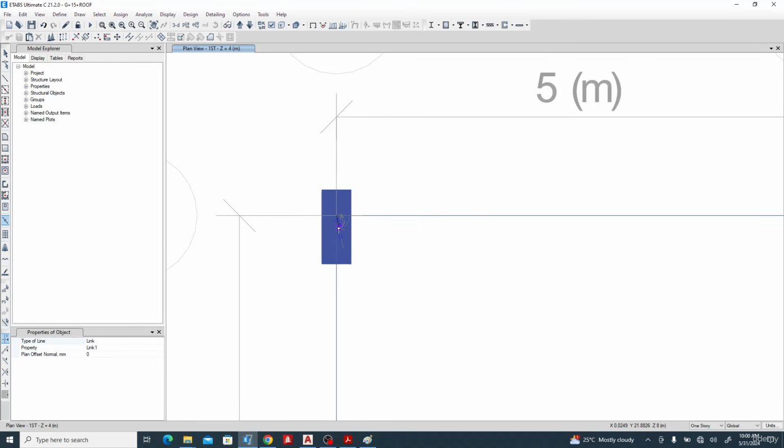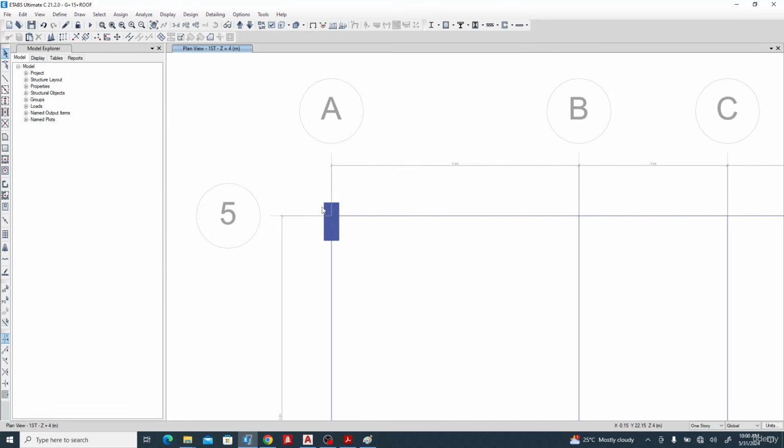Okay, now maybe the next office is okay. So you can draw these links. Okay, so it will link this to this support, then you won't have that issue. So that's the disadvantage and the complexity in modeling eccentric columns.